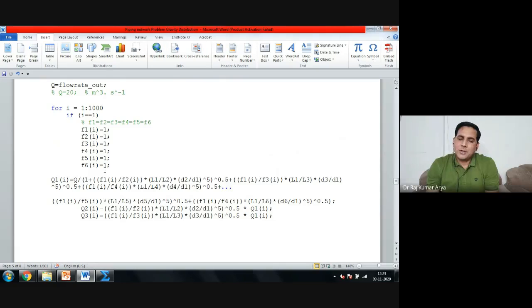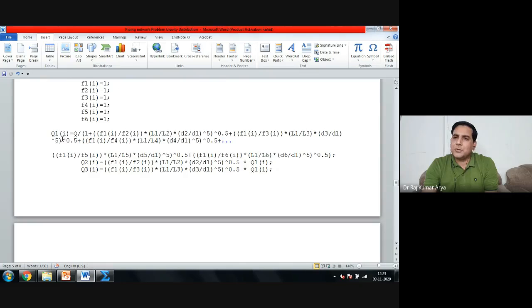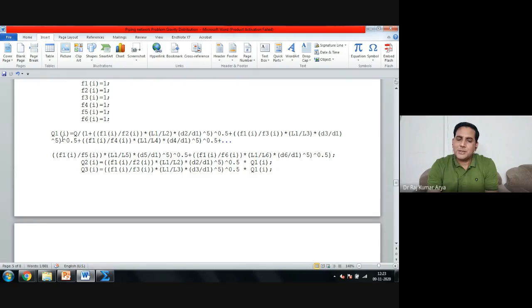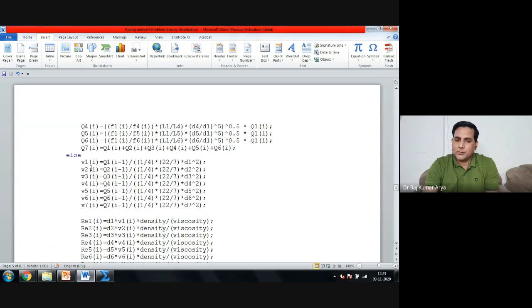I have the formula for Q from doing the head balance for each individual pipe. So I have the formula Q equals Q1 plus Q2 plus Q3 plus Q4, Q5, Q6, right? Yes, sir. I have substituted everything here. From here I will get Q1, then Q2, then Q3, then Q4, Q5, Q6, and Q7 is the other variable, the total of all flow rates. That is what we have as Q only, right?